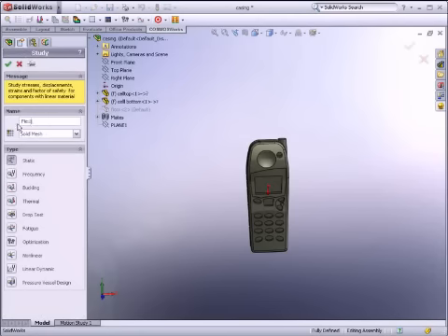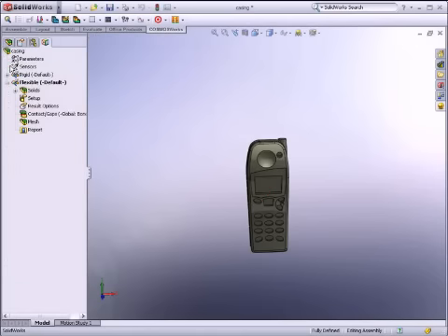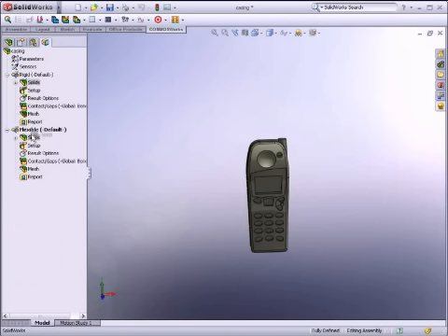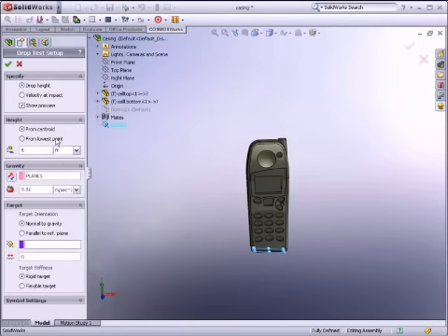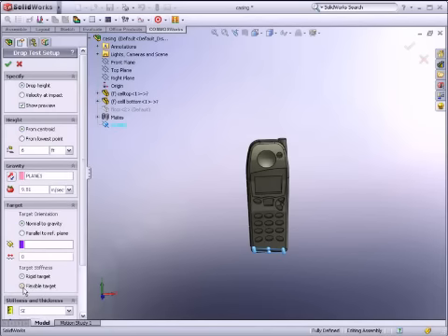However, you have the option to batch run all the drop tests once they have all been set up, thus saving time. Now we will set up another drop for flexible flooring, such as carpet. To help expedite the setup process, SolidWorks Simulation Professional allows you to drag and drop conditions that remain the same for identical models. This minimizes the need to redefine each and every part of the study.